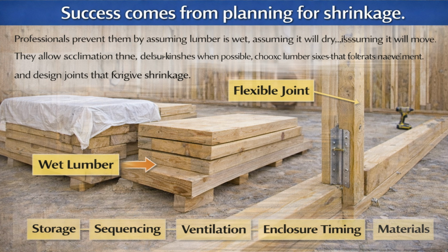Professionals prevent them by assuming lumber is wet, assuming it will dry, and assuming it will move. They allow acclimation time, delay finishes when possible, choose lumber sizes that tolerate movement, and design joints that forgive shrinkage. Moisture control is not a single step. It is a system involving storage, sequencing, ventilation, enclosure timing, and material selection.